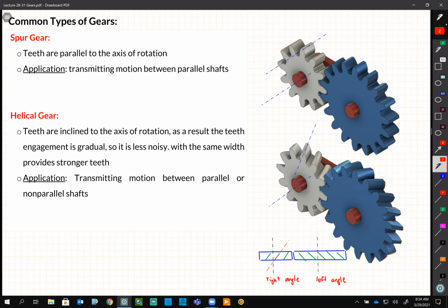And the internal gears are the same, they can be helical as well. And this angle, we call it a helix angle. We show this one by psi, not phi, psi. So next time you are buying a gear, on a catalog you'll see, okay, this is a helical gear and its helix angle is, for example, 10 degrees, 5 degrees, usually a small angle. And I showed one helical gear to you.